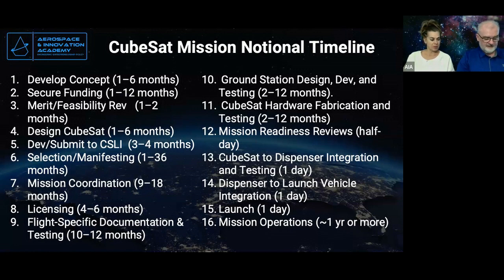What's ConOps? Those are your concepts of operation. Think of it as a flow chart of activities that happen in sequence. So your ConOps might begin with the satellite being deployed on orbit. The internal clock begins once the pins are pressed in, the electrical inhibits release, and your CubeSat powers up as soon as it's deployed.